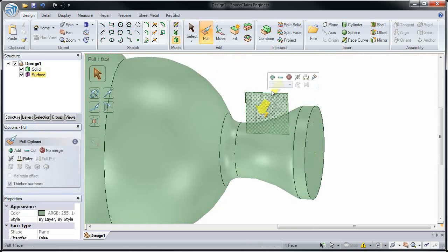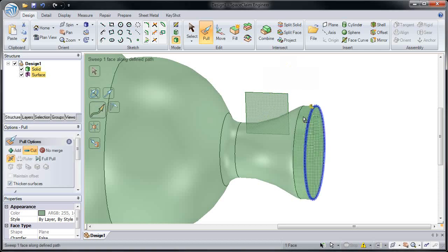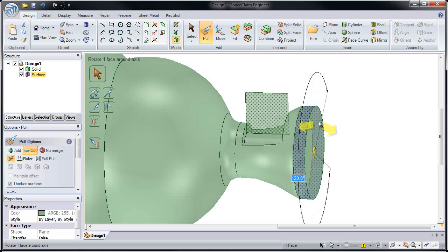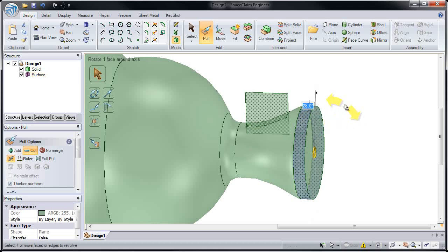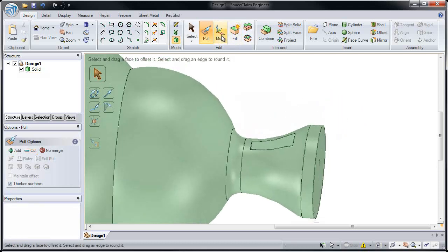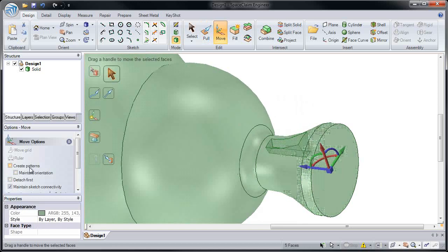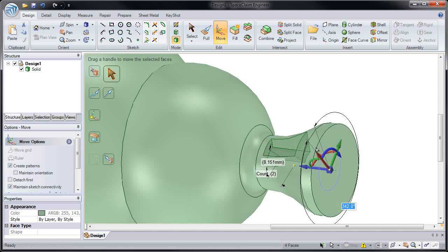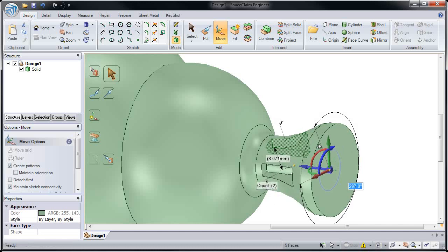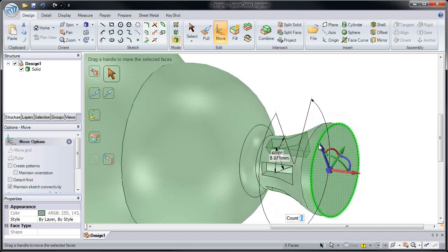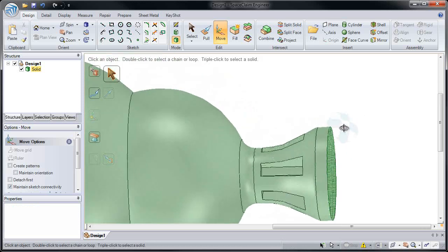So again, sketch anywhere you want on the model, and we're making all of our changes by directly editing the solid. If we want to make cuts, we'll cut the solid. If we want to take that little cutout and move it to a new location, no problem. We don't edit any features, we directly select on what we want to change and edit it. Now we have an interesting pattern all the way around.